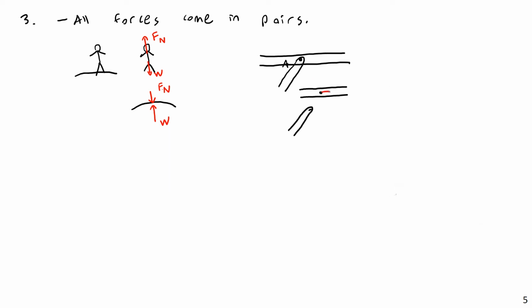So I'm going to have AX, and we'll see later that the direction that you assume is mostly arbitrary. But if AX is pushing the top member to the right, it must be pushing the bottom member to the left, equal and opposite. If AY is moving the top member upward, then AY must be moving the bottom member downward. And again, don't get too lost in this.